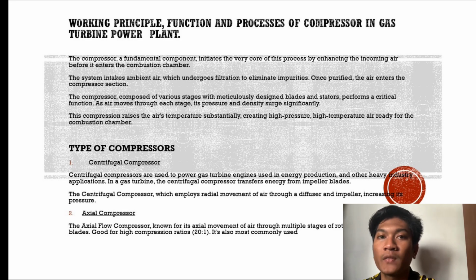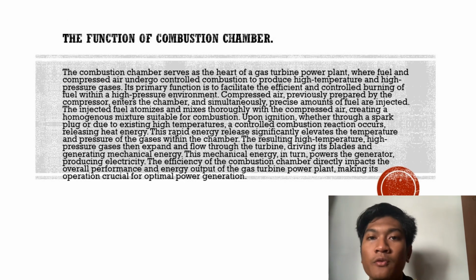Second, axial compressor. The axial flow compressor, known for its axial movement of air through multiple stages of rotating and stationary blades. Good for high compression ratio. It's also most commonly used. The function of combustion chamber.